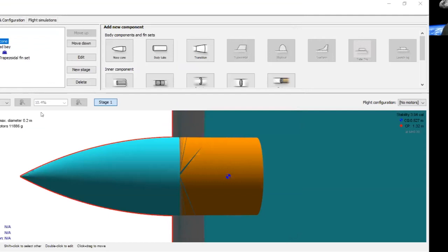And now we've got the motor in place, we can start looking at the stability, because that's how it's all affected. I'm sure you all know what the centre of gravity is. It's just simple here. If we were to tie that rocket to a piece of string, it would balance at that point. Equally important is the centre of pressure. That's the point at which, similar to the centre of gravity, all the aerodynamic forces are balanced. A way on model rockets you can test it is what's called a cardboard cutout model.